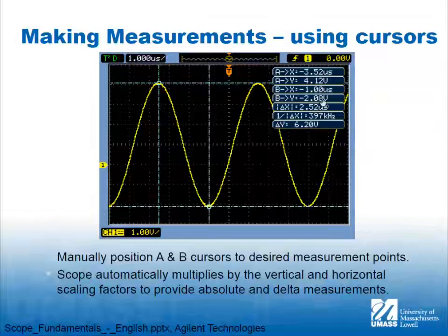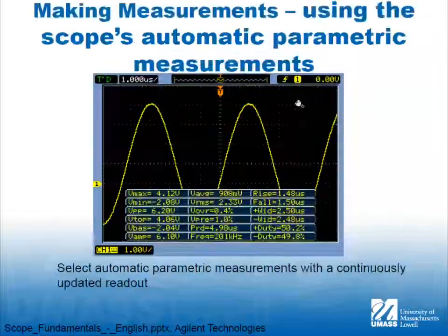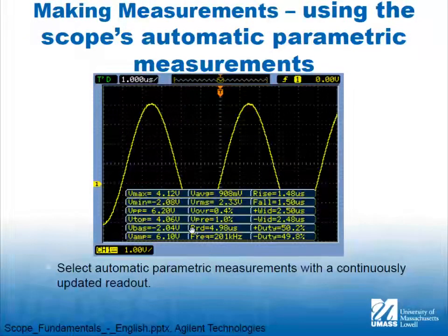The voltage measurements, again, are going to come out just as a sequence, a pattern of ones and zeros on a logic analyzer. So it will make measurements for you. So notice there's no cursors here, but we got a whole bunch of measurements. And depending on the capability of your scope, it gives you a wide range of measurements. I have about a $100 USB scope here. It doesn't have very high bandwidth, and it has all these measurements on it. It's only like 20 megahertz bandwidth, but it plugs in by USB. I probe the things I want to probe, and it comes out on the screen of the laptop.